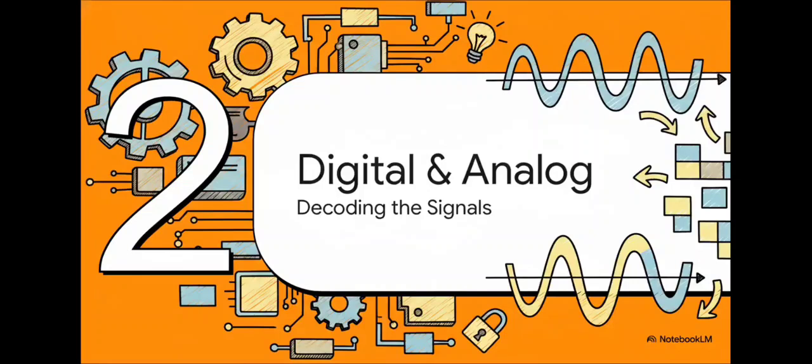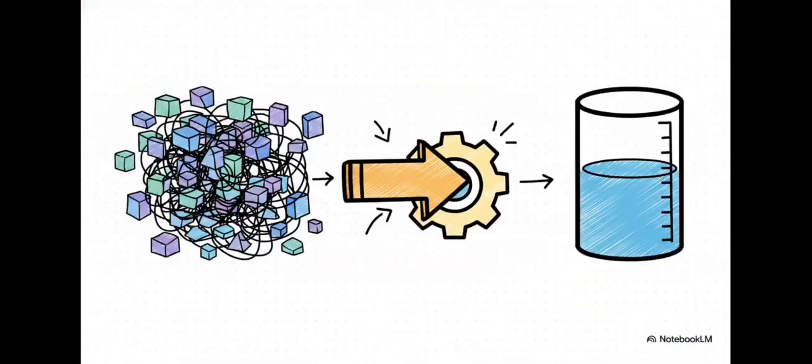That brings us to Section 2, Digital and Analog Translators, Decoding the Signals. You know as well as I do, there's a messy reality to industrial automation. The control hardware receives data in a raw, unpolished hexadecimal format, something like 16#6600. But obviously, your control software and certainly the human operators on the floor can't run a plant staring at hex data all day. The system absolutely needs clean, scaled physical values to function. It needs to know that a tank is filled to exactly 5 meters. This critical, necessary work of taking messy code and turning it into tangible, real-world metrics, that's analog translation.